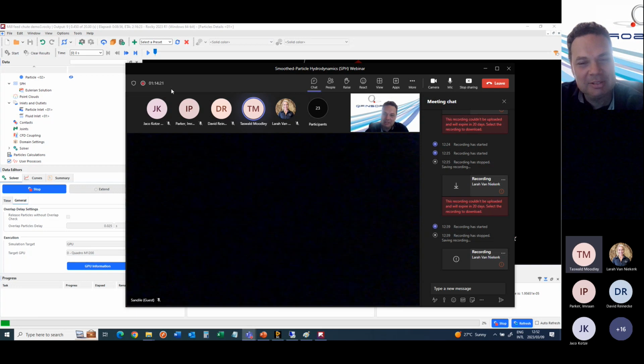Okay, and then my last one is the volumetric fill. I've played around with it, I need to fill the interstices between my DEM particles with fluid. And when I read up about the volumetric fill, I thought that that's the simple way of doing it. Just specify a mass of particles, and the seed will grow, and automatically the SPH elements will be filled inside. Now, what I noticed is that it's a very linear relationship.